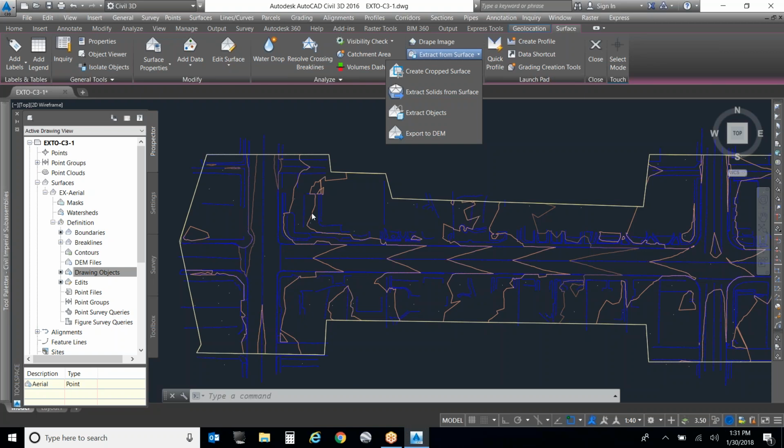So you don't necessarily want to just add those points to your aerial surface. You want to cut it out of your aerial and then paste just that small area into it, kind of the other way around. Yes. If you've got three miles of aerial and you've got 35 manholes, couldn't you just add that to your original aerial surface? Because you don't have enough data to actually build a surface on it.